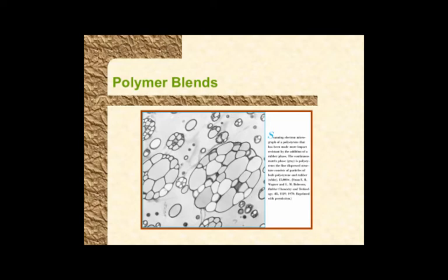One thing we looked at was that you might need to use a combination of additives, a combination of polymers, in powder processing. Lower molecular weight, better viscosity; higher molecular weight, better strength. So you might need to mix two different polymers to get a combination of good flow properties, and once it has become a solid, good strength, so you can take it out of the mold, right?